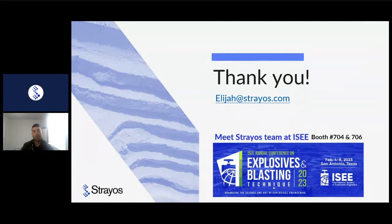So maybe understanding where your bedding planes are, the dip angles, and how that might affect your pre-split drilling can play into the outcome of it. So gathering the data and measuring it early on, before you run into an issue when you're pre-split drilling, maybe near completion, would be, I would say, the best means of adjusting for the geology.